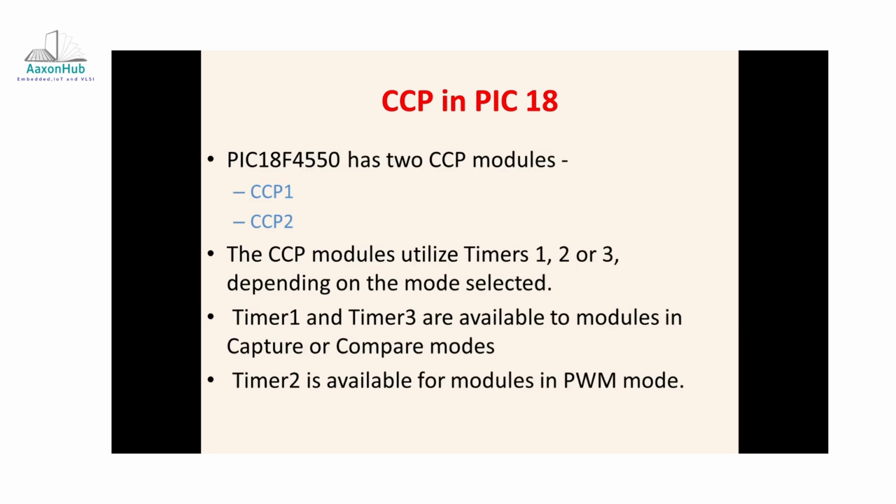In PIC18F4550, there are two CCP modules, CCP1 and CCP2. Each module contains a 16-bit register, which can operate as a 16-bit capture register, a 16-bit compare register, or even PWM.